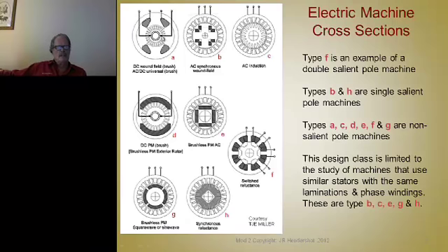So it commutates itself, it rotates, but then as soon as it rotates, it shorts out the next bar and energizes the next coil and shorts out the one before it. So rotation is continued. If you reverse the polarity of the voltage across these two terminals or across these two terminals, you change the polarity of the flux generated by either the stator or the rotor.